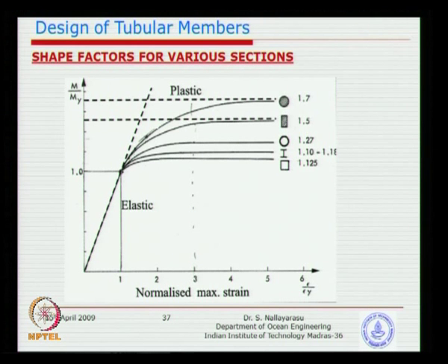What is next? This is a comparison that you can see, basically giving us the moment capacities. So, mostly if you are having a design somewhere here within the elastic limit, we may not be worried unduly whether it is circular or whatever. Whenever you have a situation where you need to look at the ultimate capacity before you decide the allowable capacity, most allowable stress designs will look at the yield capacity divided by a factor of safety, and that is your design.